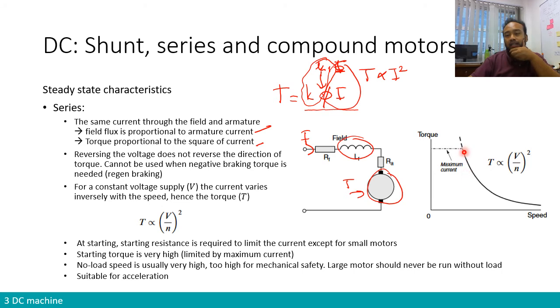So at a specific voltage, this is the curve of the machine. If you have a higher load, imagine you have a base voltage, you're going to be placed at this point. But if the load increases, the speed is going to be reduced, following this line.